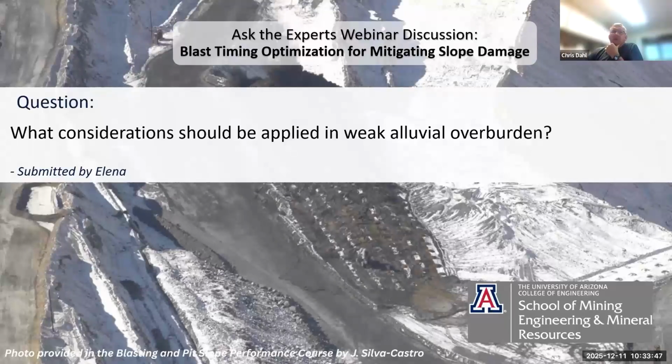Yeah, just quickly. Pat has seen it. Paul has seen it in Nevada. Sometimes the answer is no explosives. We've seen success with just line drilling, no explosives, no timing. Good success in alluvium applications, great for high wall mitigation and slope control. Just drilling a line of blast holes and being able to dig a 90-degree face to them in some of these alluvium situations.